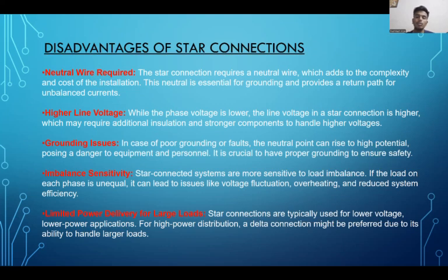Star connected systems are more sensitive to load imbalance. So imbalance sensitivity is another disadvantage of star connections. If the load on each phase is unequal, it can lead to issues like voltage fluctuation, overheating, and reduced system efficiency. Limited power delivery for large loads.